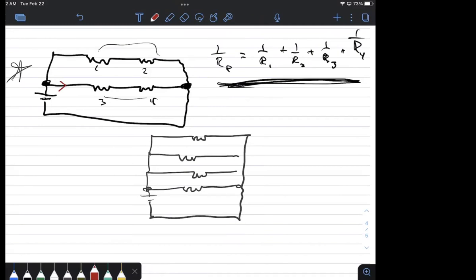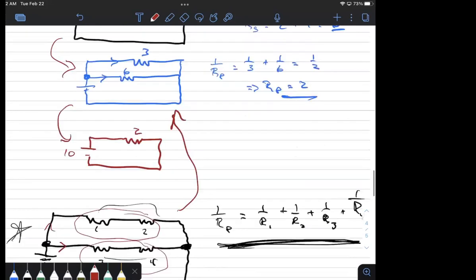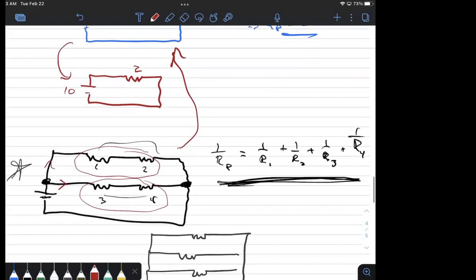And that tells you that what you have is a parallel piece for the 2 branches, but in each of these branches, there's series stuff in it. So what I would do is combine these in series, and you get some new resistance, and these in series, new resistance. And then that becomes what this looks like in blue. It's a basic 2 resistors in parallel with each other. Yeah. So that's the thing.